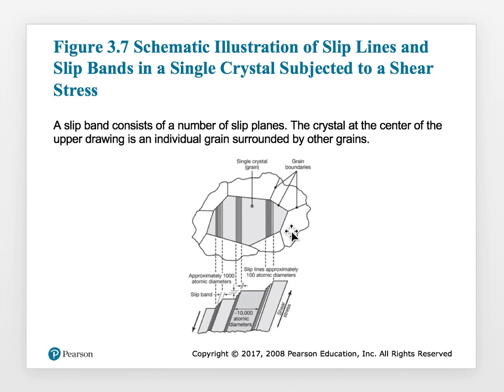And if you recall the tensile stress strain curve, you go past the area where the stress strain curve starts curving over, but you don't go enough that it goes over the hump. In which case it will start failing. You do not want the material to fail, but you want the material to deform plastically.